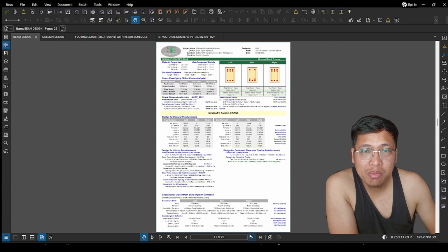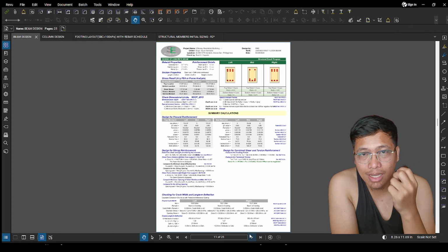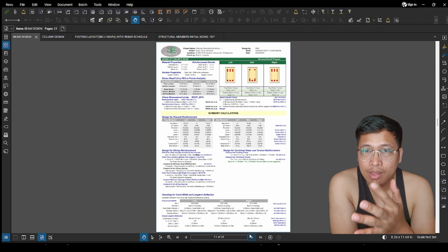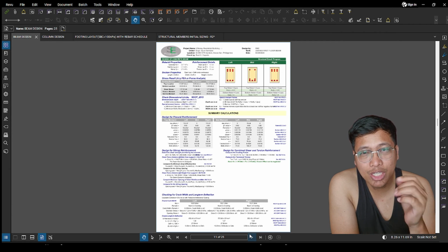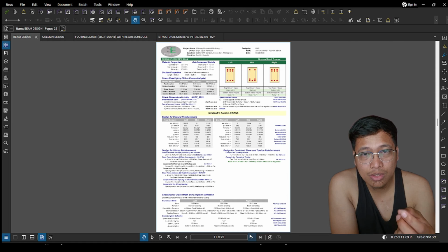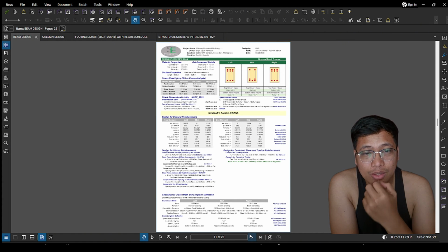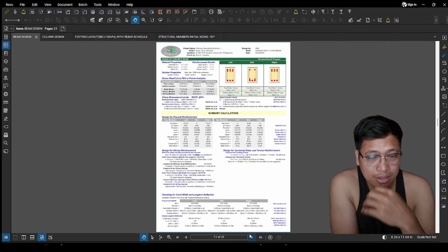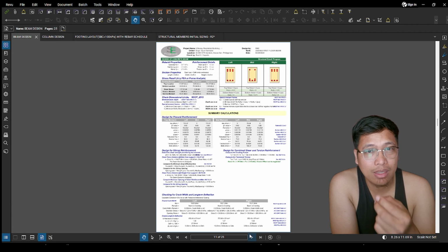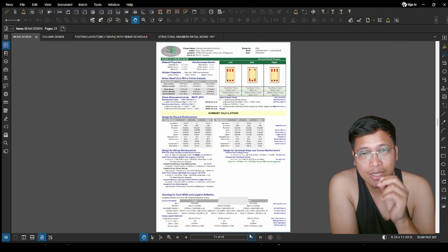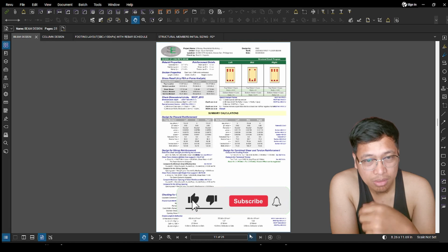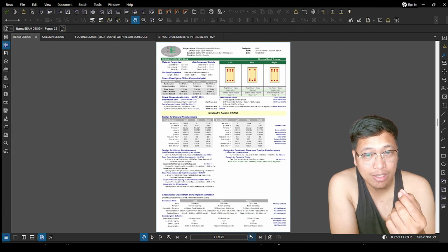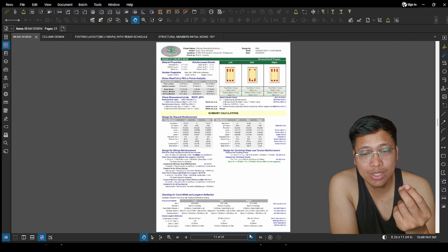So for every section, I just analyze and design only one section. I mean, one rebar schedule for each section, considering the maximum forces. So kung mayroon kang tatlong section, then tatlong design lang siya. But if you want to make it detailed and to list the rebar ratio, pwede mo yan, you can analyze and design each member depending on its corresponding forces.